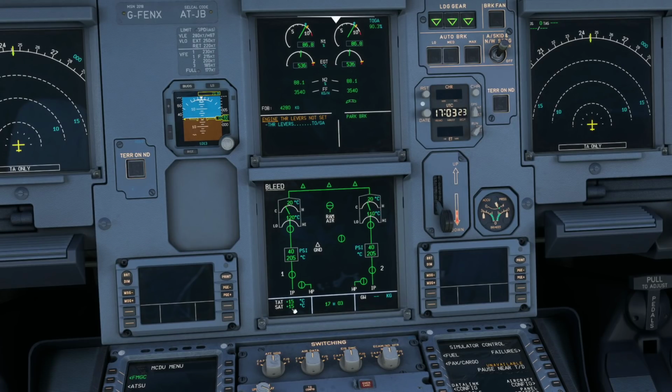And then the moment we bring the thrust back to idle, you can see there that the valve, the BMC, has basically said, okay, we now need more pressure in the system. So let's open up the high pressure valve, and we'll start feeding the bleed air system from the high pressure valve as well, so that we can get a little bit more pressure in there. So it's a really smart system, and that's the BMC's job there, is to ensure that there's a minimum amount of pressure in the bleed air system, and it does so by regulating these valves.